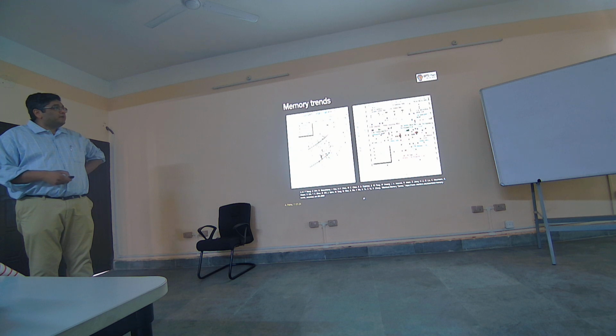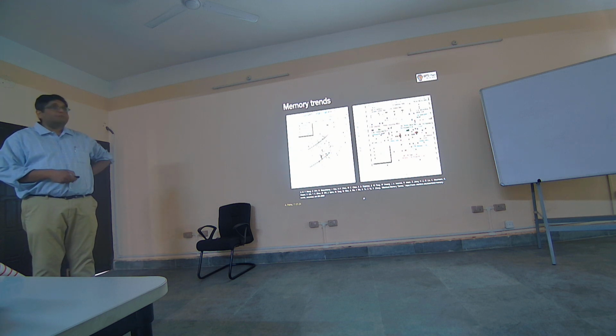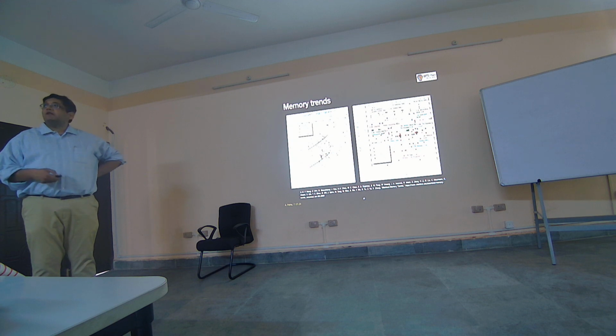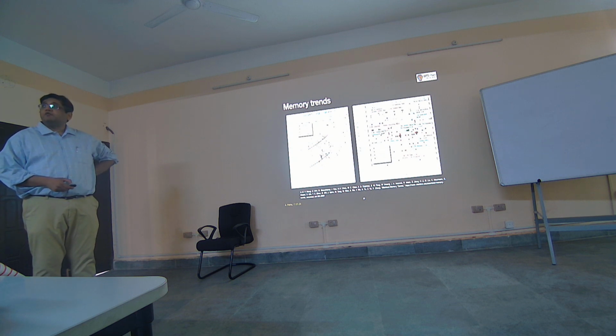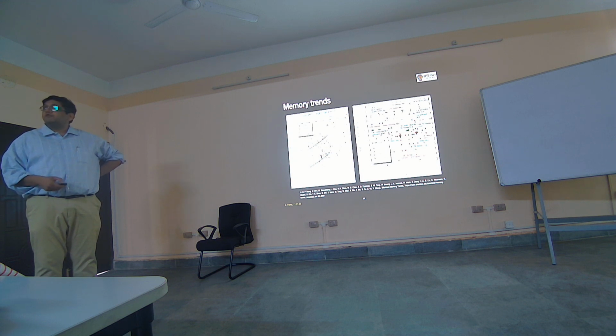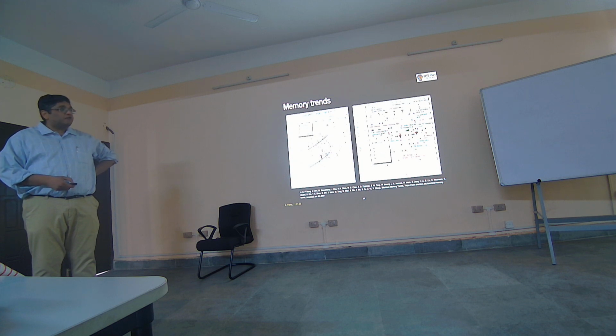And what you end up seeing is they have exhibited pretty high capacities. Right? And the problem with these memories has been with endurance and retention. So therefore they've not made it into storage classes. And the other advantage is NAND. Once it moved from 2D NAND to 3D NAND, all of a sudden we saw a huge rise in the number of bits available per unit silicon. And so therefore I think it's become very hard to beat NAND as of now.